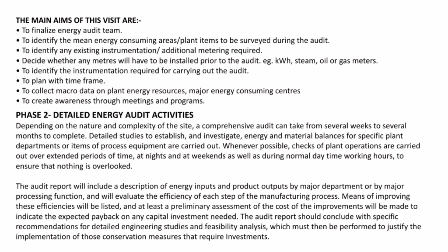Detailed studies to establish and investigate energy and material balances for specific plant departments or items of process equipment are carried out. Whenever possible, checks of plant operation are carried out over extended periods of time, at nights and at weekends, as well as during the normal daytime working hours, to ensure that nothing has been overlooked, because sometimes there may be machines which are not in working condition because they are not needed at the particular work. Sometimes they are working, sometimes lots of machines are working at a particular time. So all these have to be considered during the energy audit.